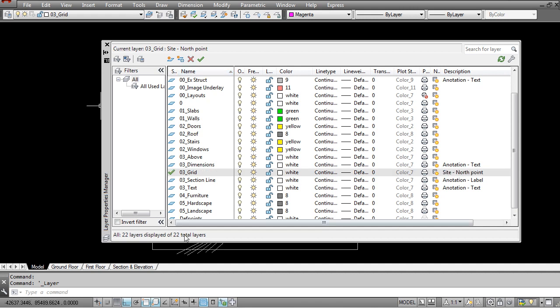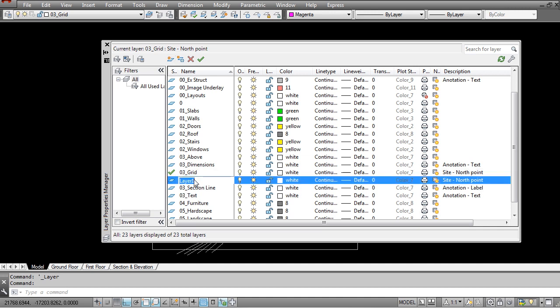So generally, once I have whichever layering system in AutoCAD, I will now make a brand new layering system that I'm going to create as we speak right now. Keeping with the same logic of having a double-digit number as a prefix, I like to have all of the CAD geometry on a 00 layer. So here I will have, for example, ground, and all of the objects that are on the ground floor will be under that layer. If you would like to create subcategories of that layer, then you can, for example, have ground contours.